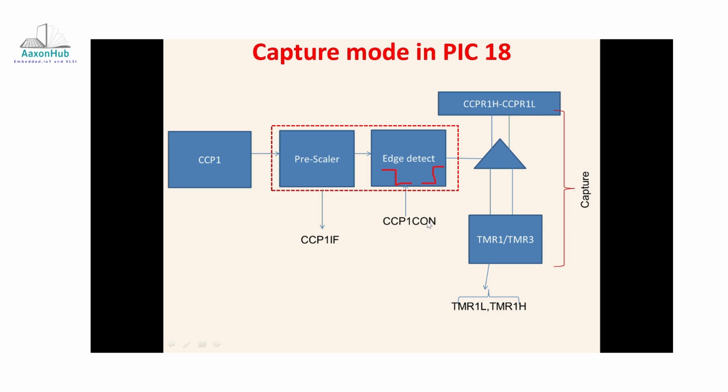For every rising edge or every falling edge, the clocks are defined in that manner. So this is the falling edge of the clock and this is the rising edge of the clock. This is the more significant meaning of this clock signal applied for edge detect. Whenever these kinds of events are generated, this particular interrupt flag will get updated.